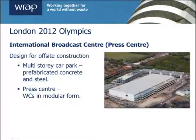The second principle of designing out waste is to design for off-site construction. 2 examples of this have been achieved at the International Broadcast Centre, also known as the Press Centre, and its car park. The multi-storey car park serving the Press Centre was originally designed as a cast in situ concrete structure. However, during the value engineering process, it was decided to change this to a largely prefabricated solution in concrete and steel in order to reduce the amount of materials and temporary works required, as well as reducing the construction period.